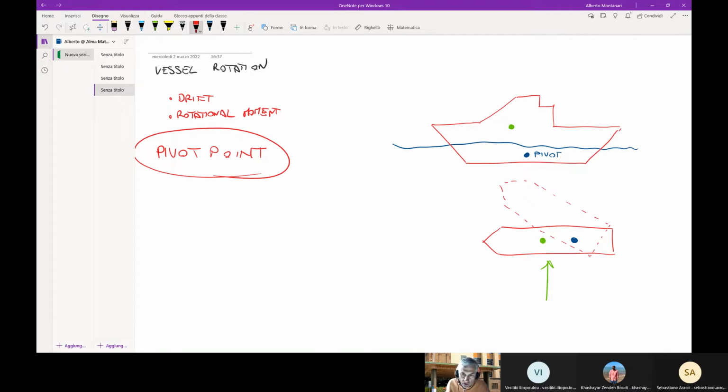And so rotation, of course, is to be considered for a berthed ship because it causes some asymmetry in the distribution of loads. And we will see how we can take into account rotation when we make the exercise that I mentioned to you. Rotation usually is taken into account when I am interested in computing the forces for each single bollard, and therefore it's not really considered when computing the distributed load, because the presence of rotation may change the distribution of longitudinal and perpendicular load over the berths, but it is usually not considered when we only consider the distributed load.